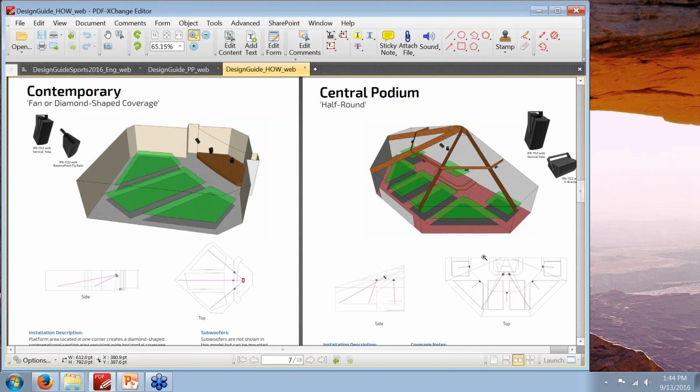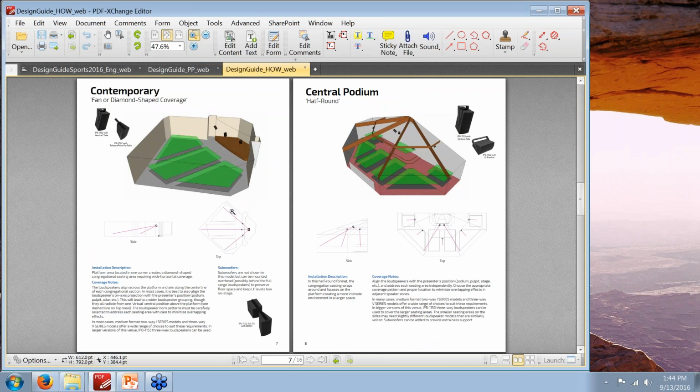And putting speakers on the back wall can be really tricky. Sometimes we can get away with using line sources there, but it gets tricky to get microphones on the platform to not create feedback difficulties. So you've seen this methodology already in the other booklet, and it just sort of carries through. Just looking at the space from its floor plan and looking at a layout that radiates sound from the presenter area.